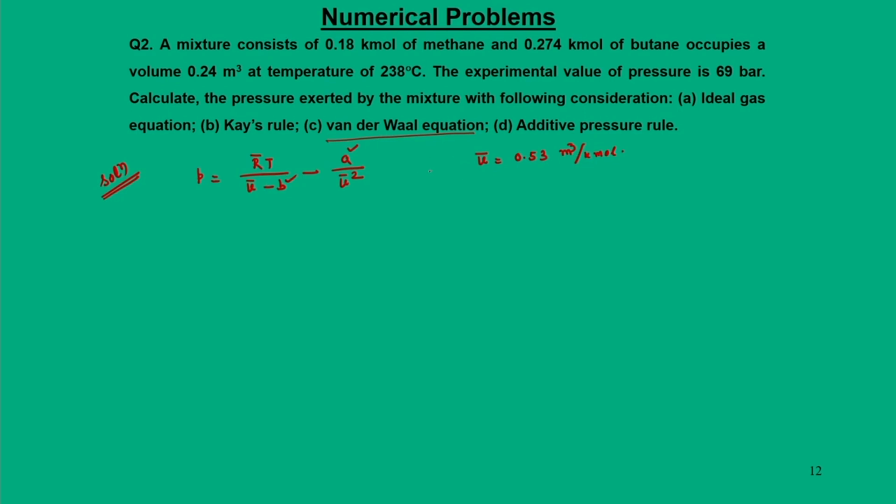To do that, we have to find for each case, like for CH4 we need to find from the data sheet what is A1, it is 2.293, B1 0.428, we also evaluated Y1, its mole fraction, 0.396.